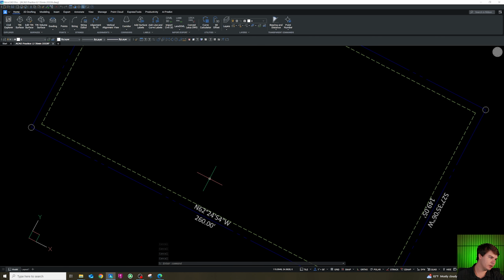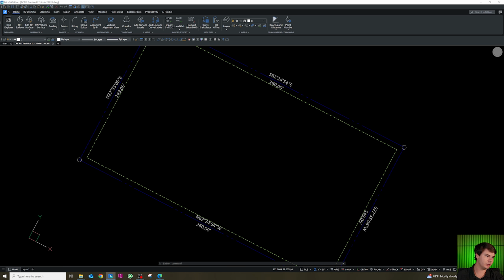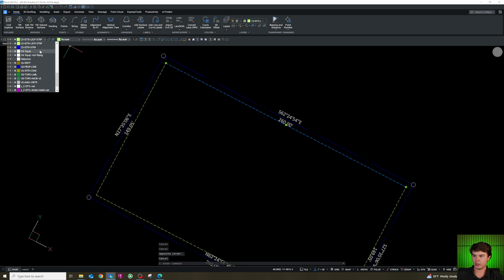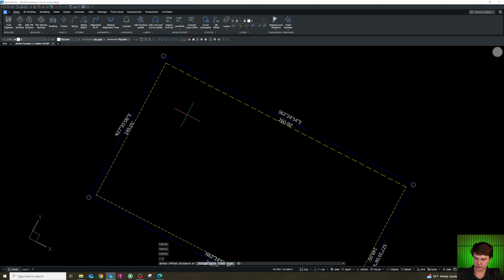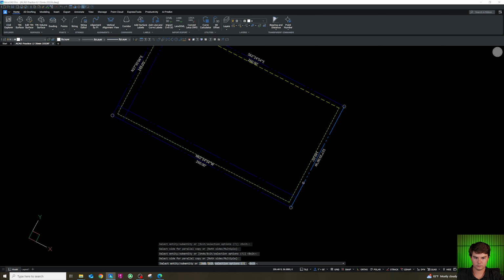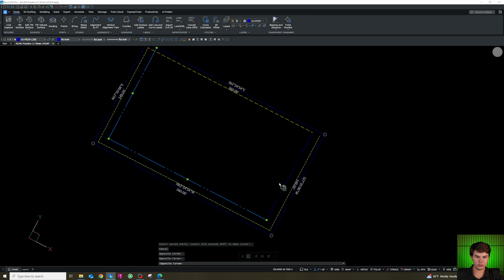Now we'll do our building setbacks. Doesn't look like we have any to really worry about except for this rear line, which we have our building 5 feet. So we'll do a 5-foot building setback line. And then the rest we can just do 15 because our building does not get close enough. We'll connect these with a 0 radius. And then put our lines on the building setback layer.